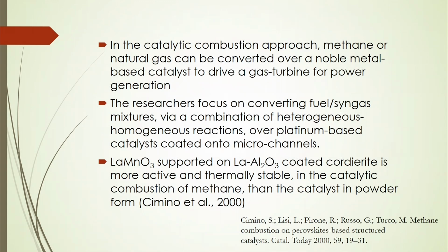In this case, the researchers focus on converting fuel or syngas mixtures by a combination of heterogeneous and homogeneous reactions over platinum based catalyst coated onto microchannels. Even other metals supported on coated cordierite. Cordierite is more active and thermally stable in the catalytic combustion of methane than the catalyst in powder form.